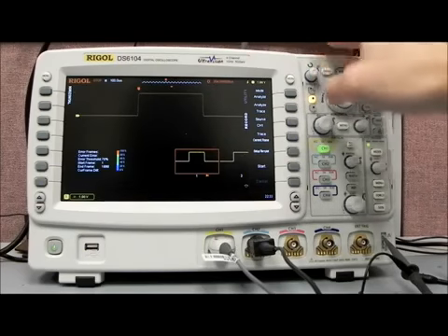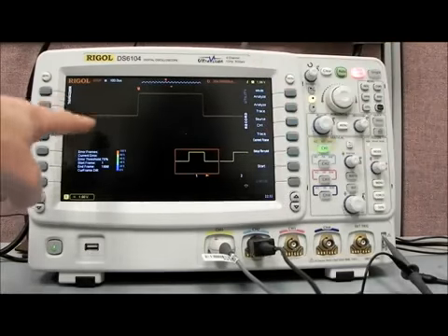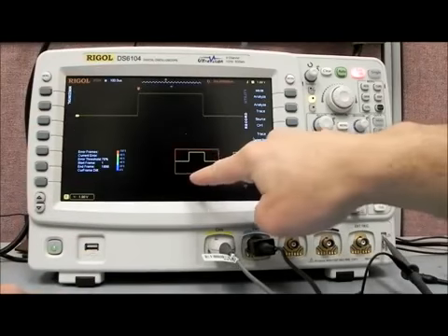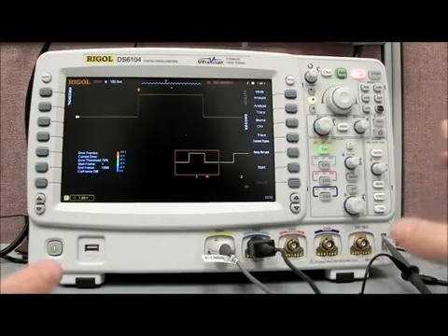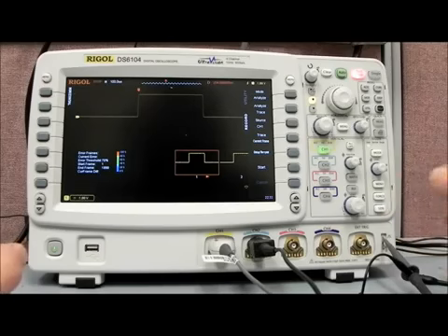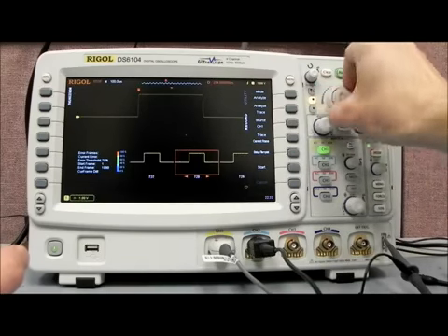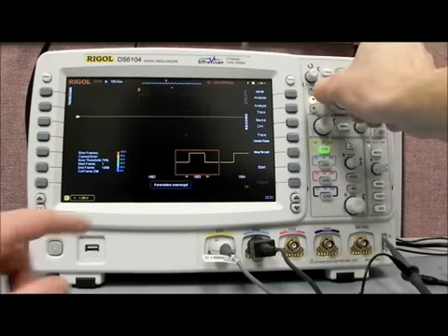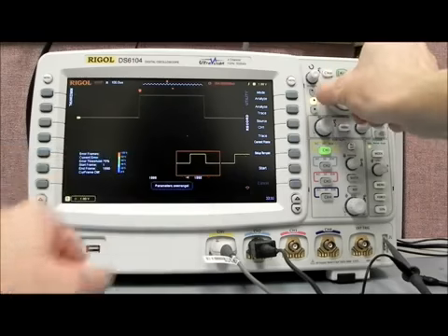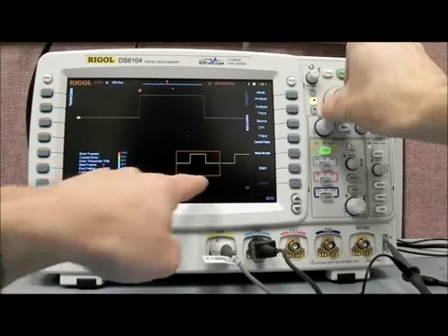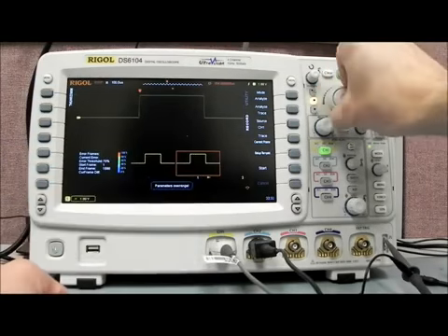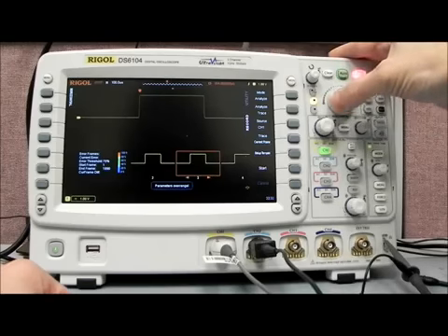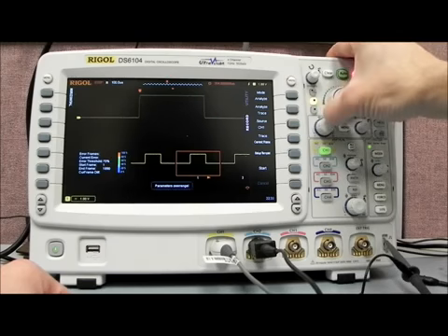In Analysis, you'll see now we have a split screen. On the top screen, we have a picture of the first frame, or the first waveform that we've collected in memory. We can select any number of those by using the outer Ultravision knob, which gives us a fast-forward effect. You can see that we're zipping along now, we're at 1,890 frames, or we can go one at a time using the inner knob, where we go 5, 6, 7, 8, and back again.